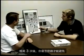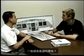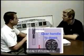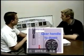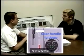Okay, after cranking it 3 times, what would you do to not get some of the warnings? I'm going to go ahead and put the gear handle down. Match the gear handle with the gear. Another idiosyncrasy with cranking the gear down is that I'm going to lose the nose wheel steering.